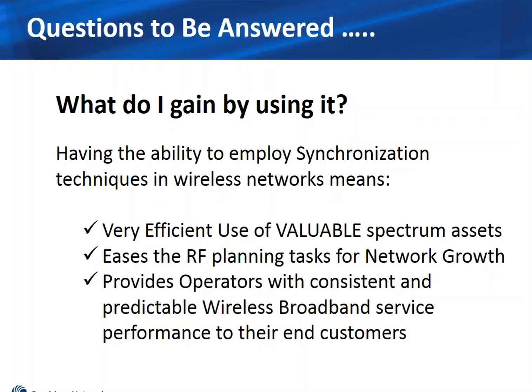Easing the RF planning tasks for network growth. So also with this ability, and we didn't really use this term so much, but with a synchronized network, it enables the ability to reuse frequencies on the same tower, because I'm not going to be self-interfering with these other radios if I have all my transmit and receive duty cycles, TDD cycles, synchronized.